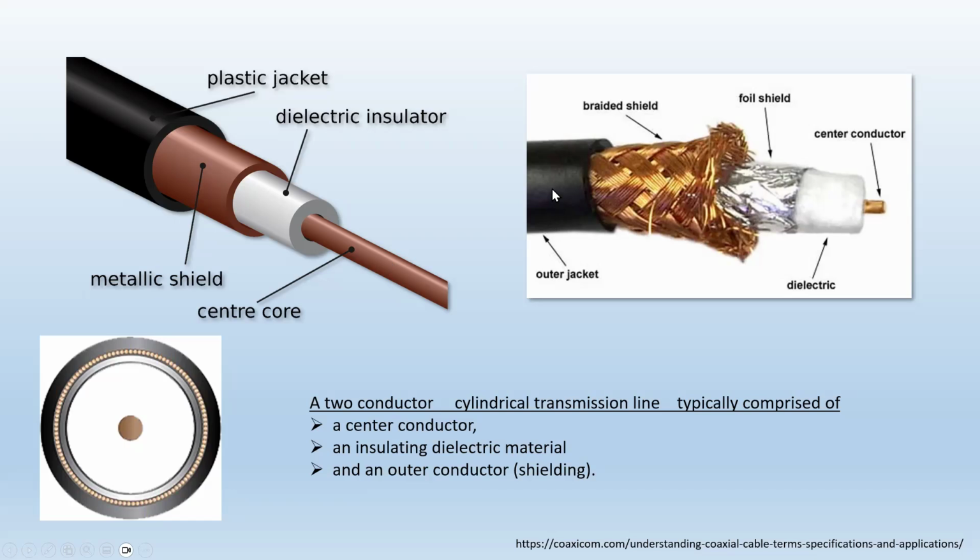If you see that U printed on the jacketing, it means the cable is UV rated, which means it can be installed outside, exposed to the sun, and it should be okay. If it doesn't have that U, which means it's not UV rated, and you install it outside without any protection from the sun or any enclosure, within a year, if you just grab it with your hand, you can almost crush it into a powder. Right? Talking about the jacketing.